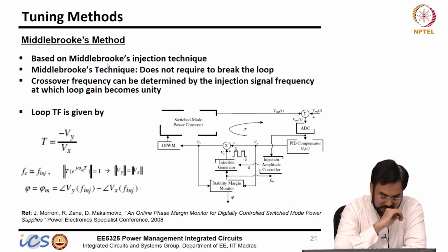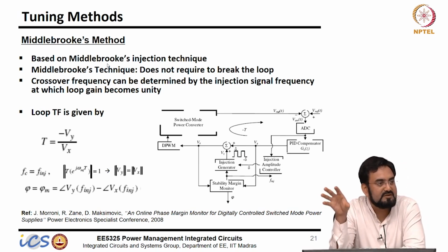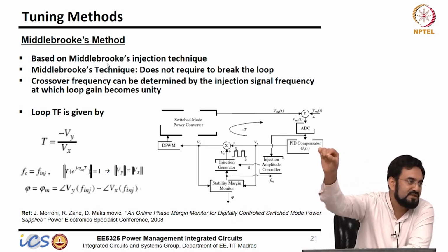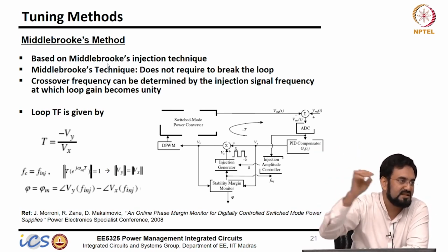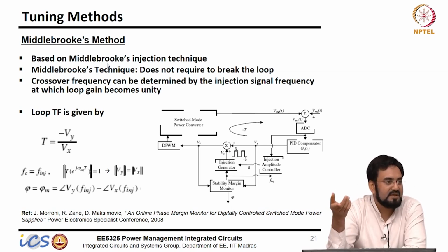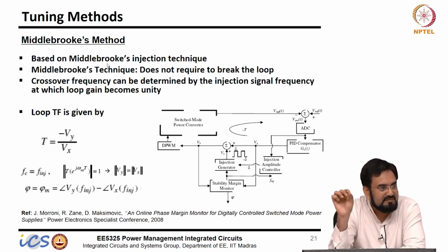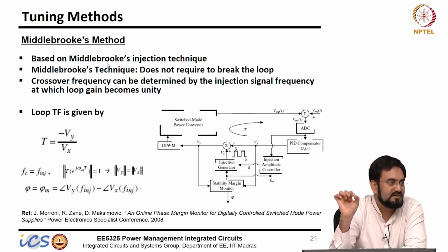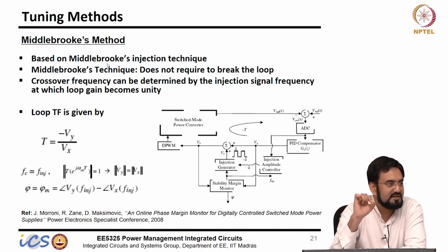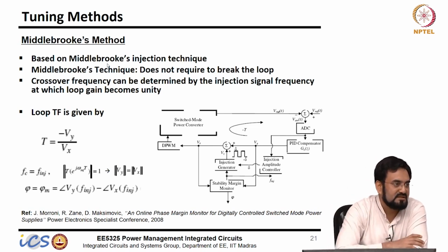So one way to look at your phase response, when we open the loop, is to look at the UGB and what the phase margin is at that point. But if you look at the closed loop, what will happen? That will be unity gain, and whatever phase you get there will basically tell you the phase margin.